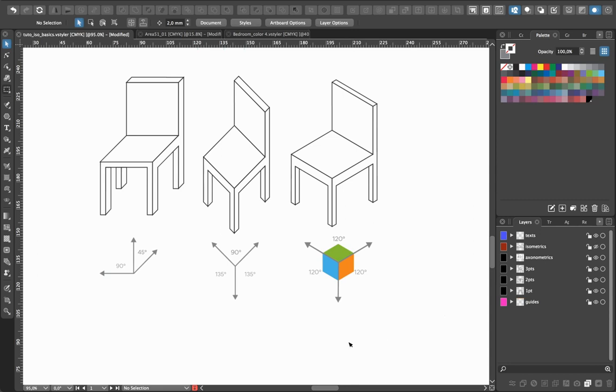So here are three different kinds of axonometric perspective, and as you can see, the angle is different. Why are there so many? Actually, on this kind of technical drawing, the purpose of each is to emphasize one side, one part of the object that you want to show. For instance, the first one, depending on the depth ratio, can be called the cabinet or the cavalier. You can see that this one is really focusing on the front view of the object. You show some depth, some volume, but this front part is more important.